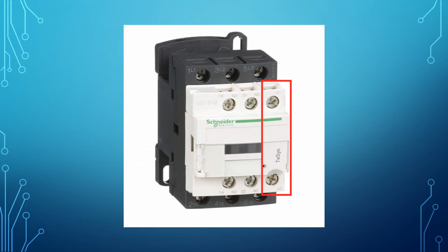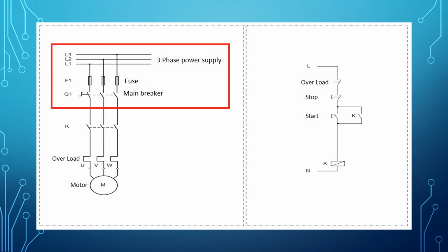If there is no problem with the control circuit, then the main breaker will be switched on, and the push button will be pushed to turn on, then the voltage over the coil A1 and A2 will be measured by the voltmeter. If the voltage is below the required, then the power circuit should be tested with the voltmeter to identify the problem. If the voltage is matching the required, but the contactor is not contacting, then the contactor should be replaced.